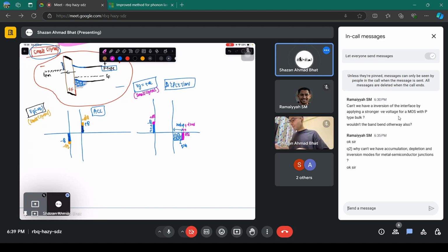This indicates that a small signal does not disturb the system to a significant extent. It does not change the region from depletion to inversion or inversion to depletion. Only gate voltage VG controls that. The small signal is important for frequency analysis only, when you operate the device and study it. That's what we are going to look into.